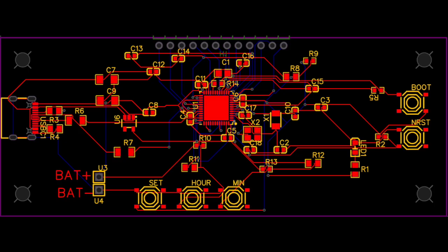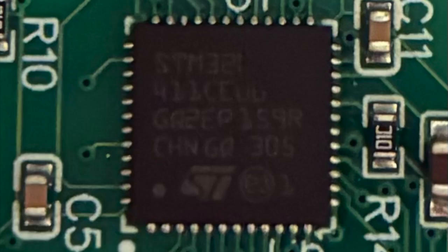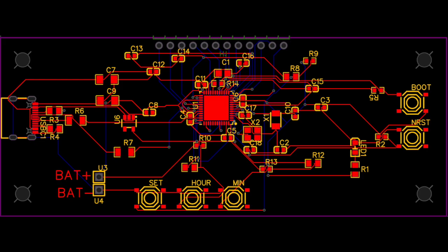This is the printed circuit board, or PCB, designed to physically connect and support all components of the CharlieClock project. A main goal is to pack all of the components to control 132 LEDs into a compact, reliable layout. At the heart of the board is the STM32 microcontroller, positioned centrally to minimize track lengths to the LED array and peripheral parts. Shorter traces can reduce signal delay and noise, which is critical for accurate multiplexing of LEDs.